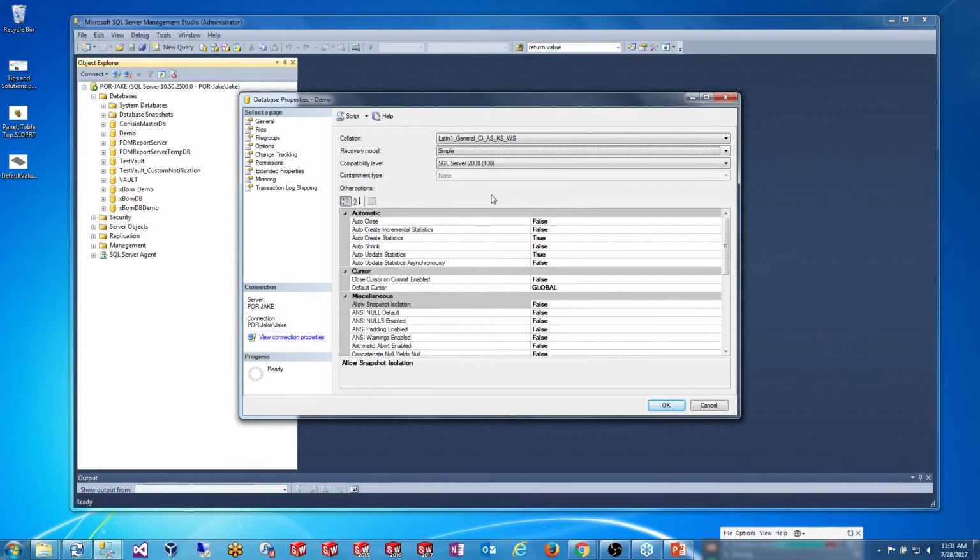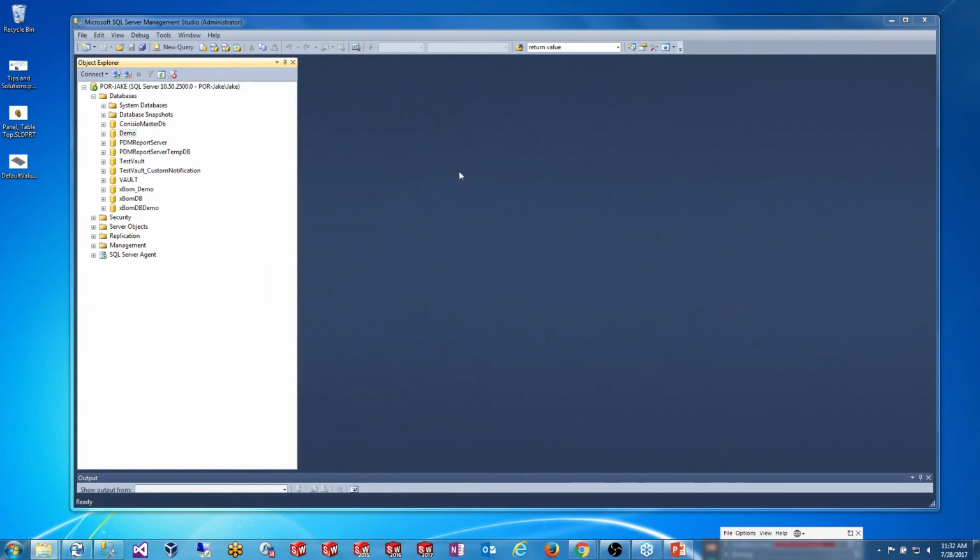You want to make sure that the database and the archives, which is the physical files that are being stored on the server, line up exactly. So making sure you're taking full backups of your database probably every day, I would say at least, is best practice, as well as setting the recovery model to simple, and that should get you going where you need to go. And making sure that you have some automation happening in here, so automatic backups is key to keeping your workload down as an IT person or as a PDM admin.